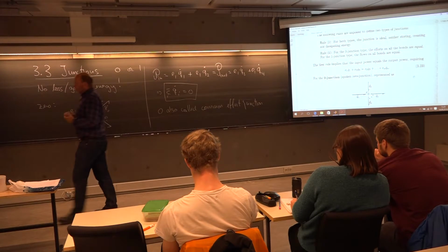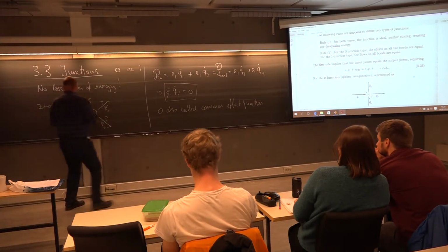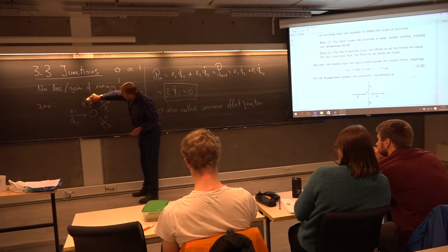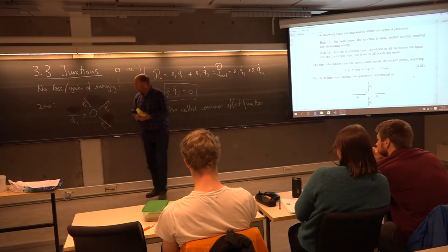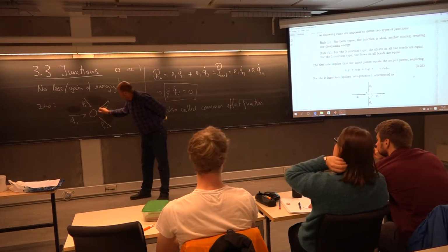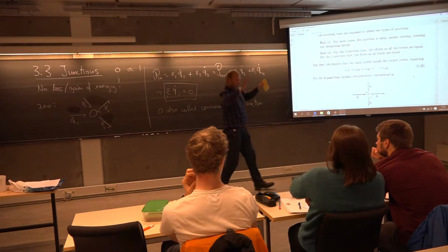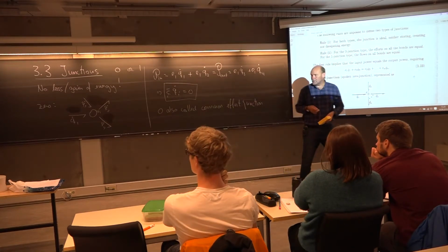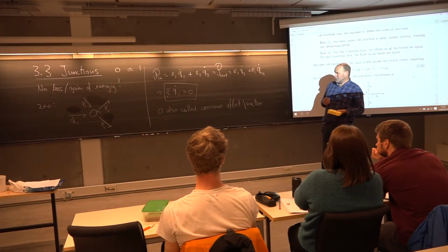And in a bond graph, to make it simple, typically you won't write all this effort E1 on all these bonds. But you could use either a superscript or a subscript or something around this 0. Here somewhere, just write E1. That means all the bonds connected to this junction will have the same effort. That's all.